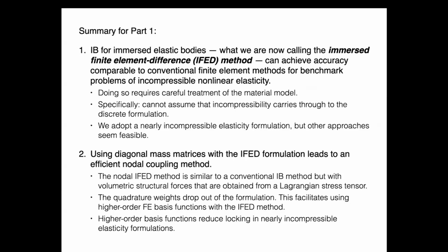But to get this to work well, you do have to be careful about the way that you treat the material model. In particular, you can't assume that the incompressibility that shows up in the continuous equations carries through to the discrete formulation. So what we do in our production runs is to adopt this nearly incompressible elasticity formulation. There are other things that you could do, but this is what we've been doing that seems to be pretty effective.